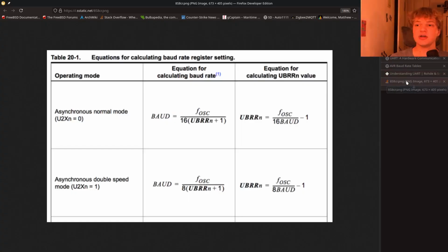And to calc that, calc is short for calculator, by the way, I'm just using slang, you use one of these formulas here. This is specifically for an AVR, but for most MCUs, it's pretty similar. I'd just check the datasheet to make sure that you're doing it right and to know what register you set. But for an AVR, for instance, here you can see the register that you set in order to determine the baud rate. It's calculated relative to the frequency of the chip, obviously, because the baud rate is a predetermined bits per second time.